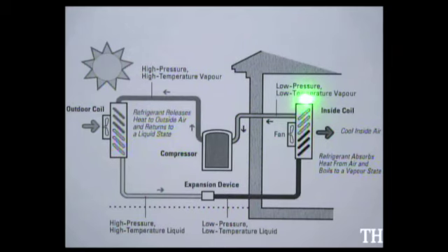On an AC unit, this inside coil would be the cold unit, and outside, the condensing unit would be the hot unit. Now all you're going to do is take the inside coil and make it the hot unit, and the outdoor coil is going to be the cool unit. Again, all you're doing is using a reversing valve to change the flow, the position of the refrigerant. By reversing the flow of the refrigerant, the two coils, the evaporator and condenser, are reversed.